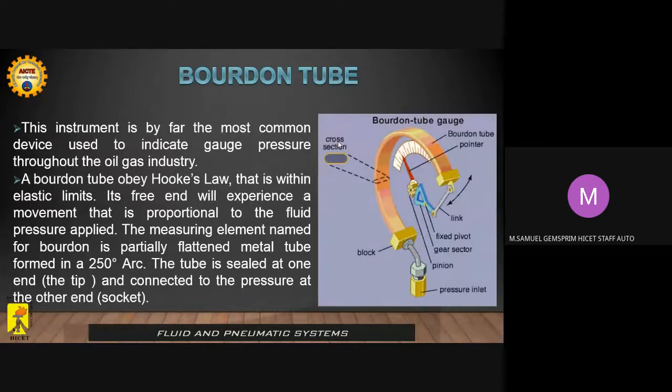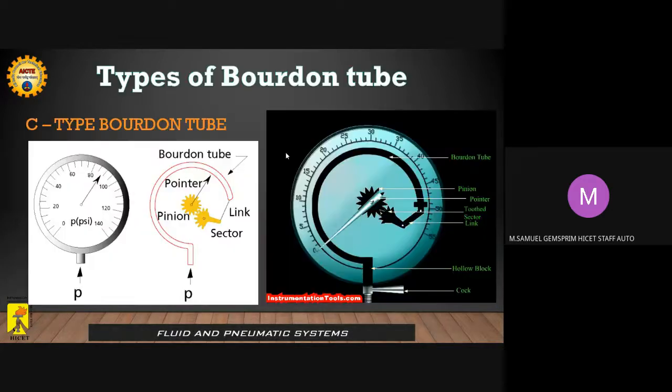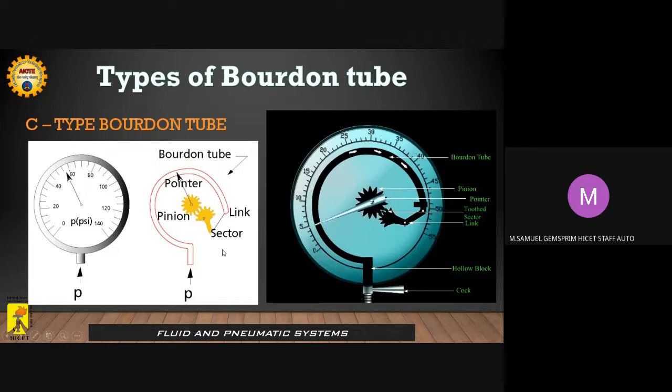Thereby, when the pressure is increasing, obviously it gets deflected, and once the pressure is released, obviously it gets back to its original position, and it is also supported by spring force. So let me show you. Here we have the animations of how it is working, so that we can very easily see the Bourdon tube, which is the C-type tube,